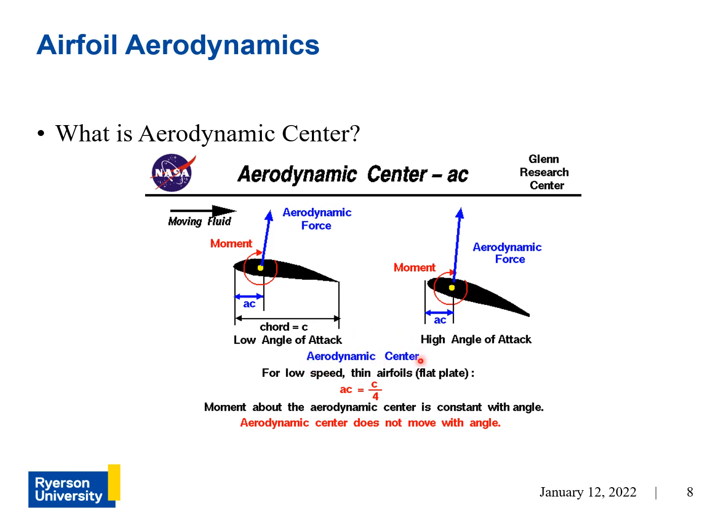The aerodynamic center is strictly the point at which the moment doesn't change as you change the angle of attack, and the center of pressure is just the location where the vertical forces caused by the aerodynamic flow balance.